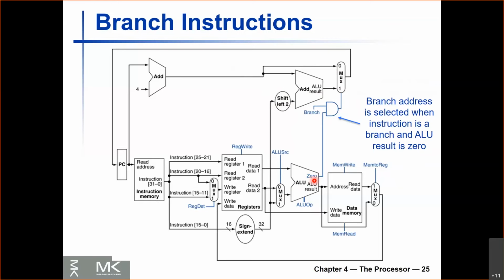Okay, thank you. Remember how when we implemented this ALU, to get this 0, we just had a big NOR gate, and we gave it all the bits. And if all the bits were 0, then this flag will be 1. Otherwise, it will be 0. Remember that? I thought it's only specific to the branch. Okay, thank you. No, it's not specific to the branch.